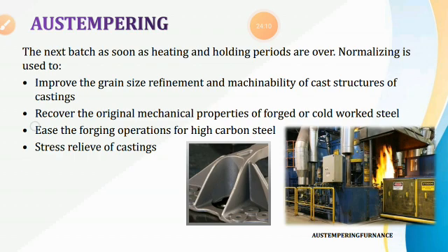Improve the grain size, refinement, and machinability of the cast structure of the casting. Recover the original mechanical properties of the forged or cold worked steels. Ease the forging operation for high carbon steel and stress relieving of castings.